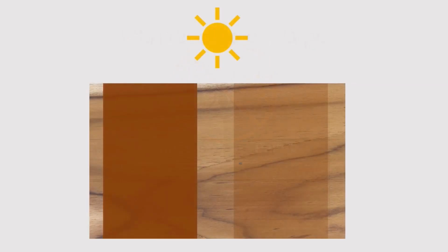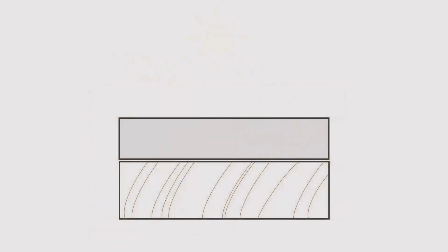Pigmented products offer better protection from ultraviolet radiation since they block sun rays before they reach the wood, making them more resistant to weathering. However, these products cover the wood's desirable aesthetic properties, such as grain and texture. In contrast, clear coatings bring the authentic wooden surface to life, but allow UV rays to penetrate and absorb into the wood. While film-forming coatings are marketed as long-lasting, they do tend to crack and flake if not maintained regularly.